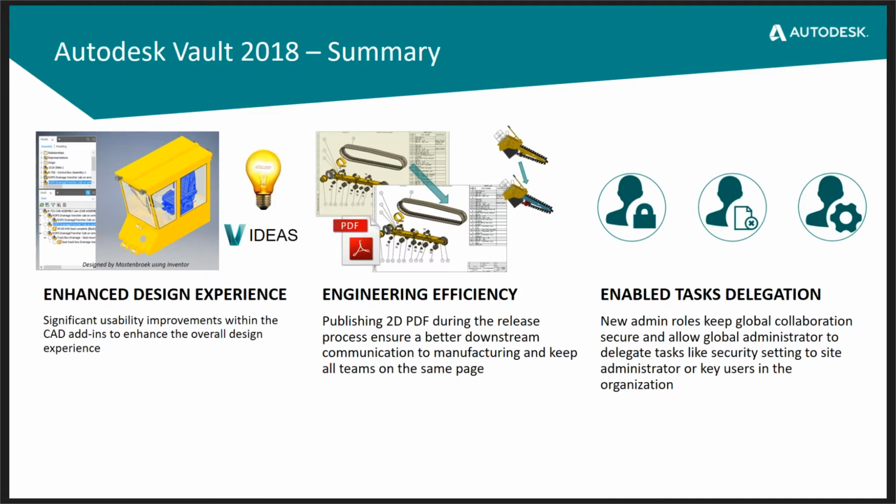You're going to be able to save that native IDW or DWG file down. Once you bump the rev or go to release, the only trigger is to go from anything to released. Once that happens, it generates that PDF for you, and you can go ahead and share that file with everybody, as opposed to giving people your IP, your full actual model, and things like that when you're giving them the IDW file or DWG file itself. Just a couple things they added in 2018.